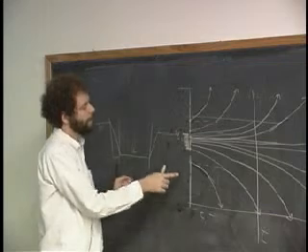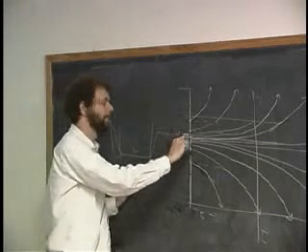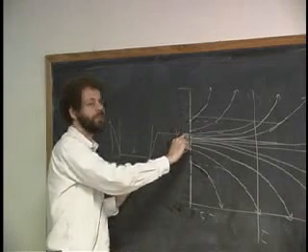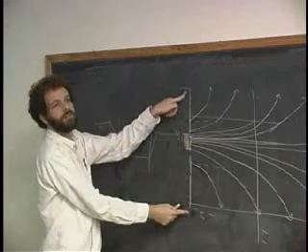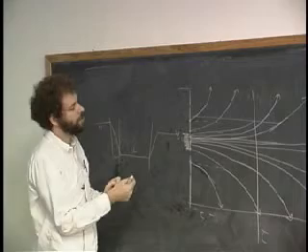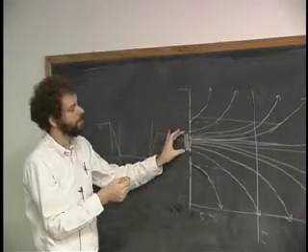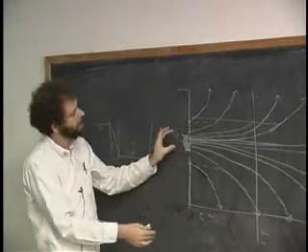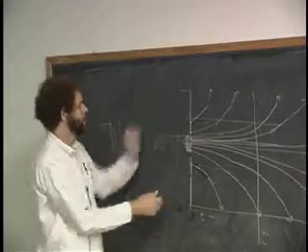Therefore, the chance that it falls inside of this range is just this range divided by that range. Does that make sense? Okay, good. So the chance that a system will be metastable past time t is just this distance divided by that distance.